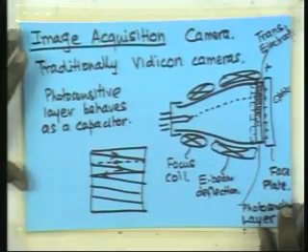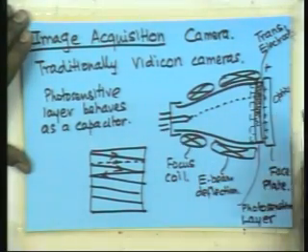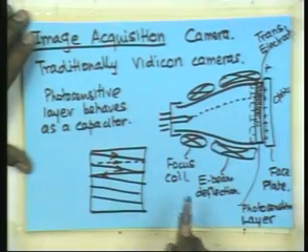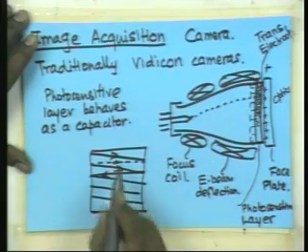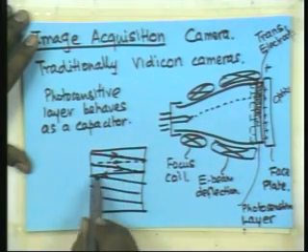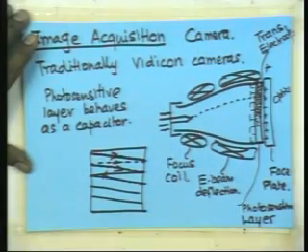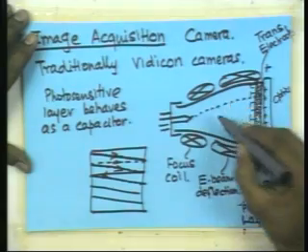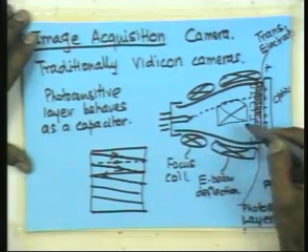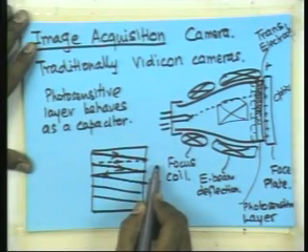So this is basically when I'm looking from the front or from the back, then I'm seeing this portion here, which is a rectangular plate. I have electrons coming and striking at these points, meaning all throughout as it is being scanned. If I use the horizontal deflection coils here and ramp up the voltage on these, then the electron is going to move with some uniform velocity across.